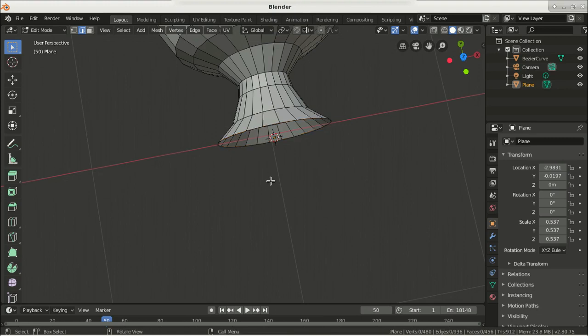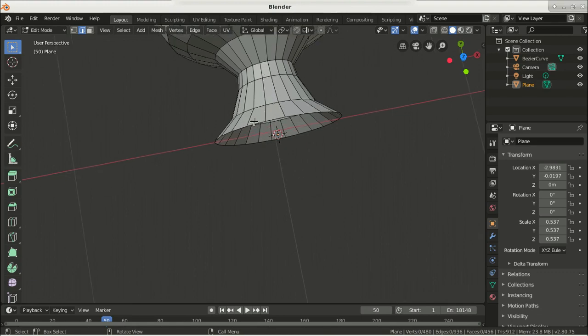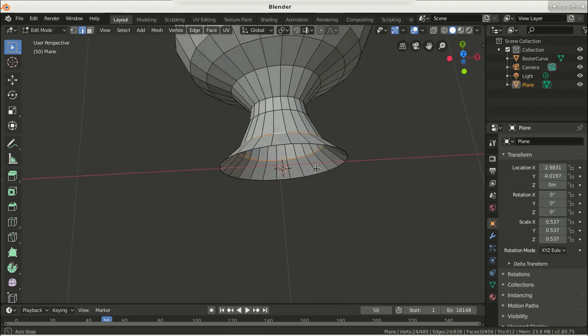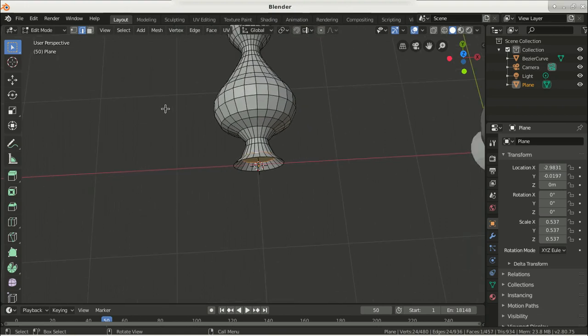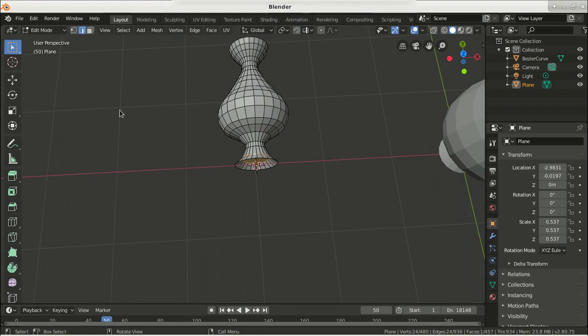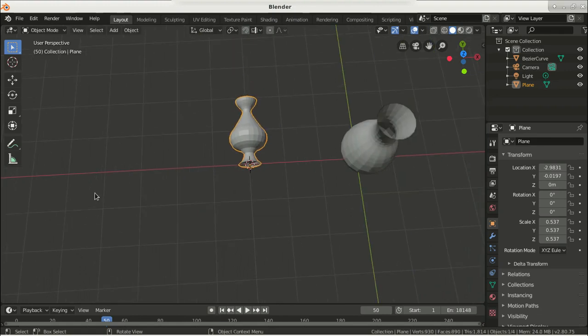Let's undo the selection. Suppose I want to create a face along these edges instead of these. So instead of selecting this loop of edges, I will select, Alt Shift click, this set of edges. You can see it from here, and I press the F key. Now the face is created here to make it more realistic. So our shape is done, it's complete.